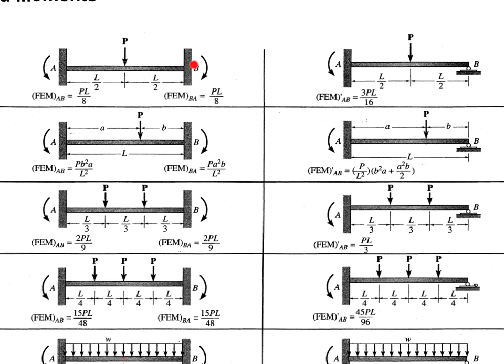It's not what's called cantilevered. Remember, these are cantilevered. So this bridge or this structure, this beam, it's really called a beam, is embedded into the wall on both sides. Here, it's not. It's just resting on the surface. When something rests on a surface, it cannot provide what's called a moment. It cannot provide a torque. So you'll notice there's no fixed end moments on any of these. See the difference? All of the moment has to be prevented rotation from here.